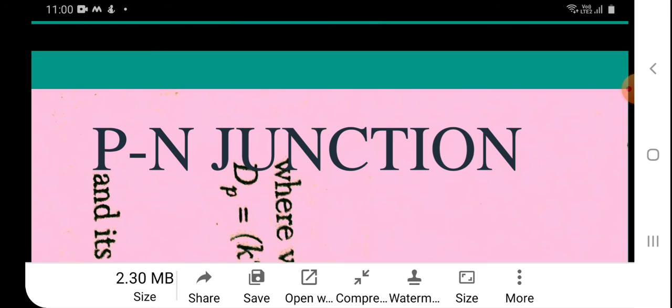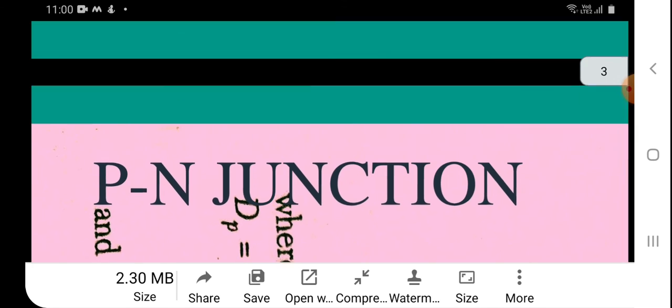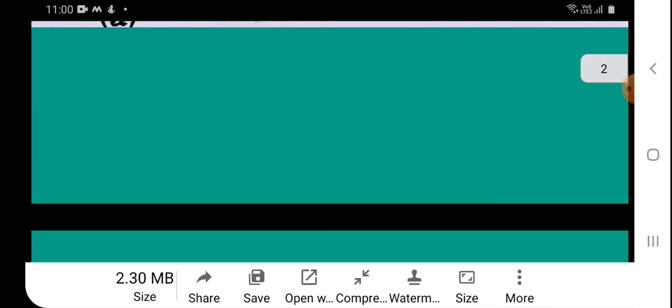For typical pn junctions in silicon and gallium arsenide, the width of each transition region is small compared with the width of the depletion region. Therefore, we can neglect the transition region and represent the depletion region by the rectangular distribution as we have shown earlier, where xp and xn denote the depletion layer widths of the p and n sides for the completely depleted region. With p equal to n equal to 0, the equation finally becomes d²ψ/dx² = q/εs (Na - Nd).